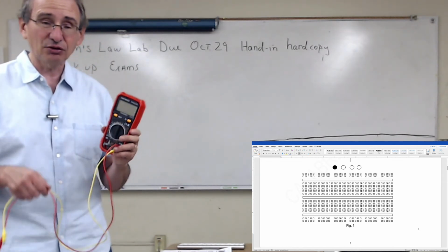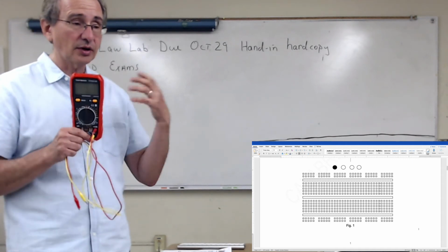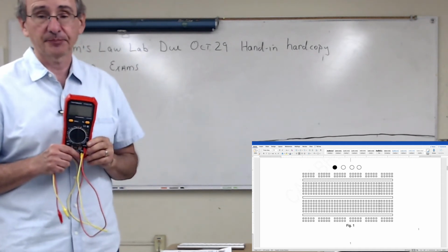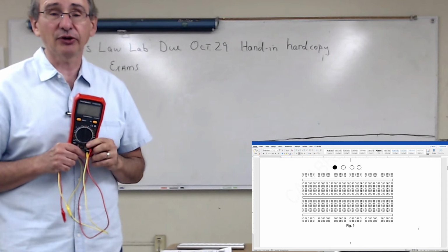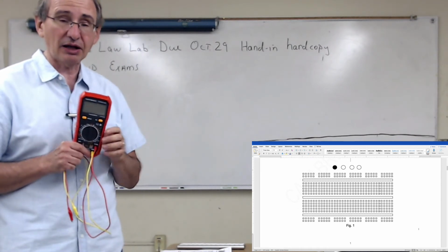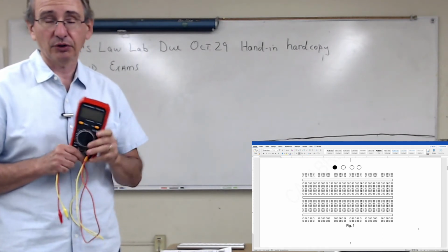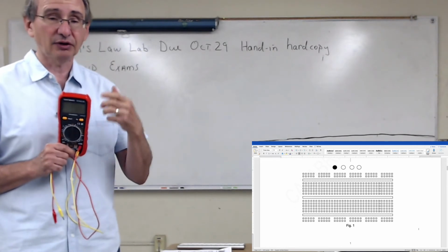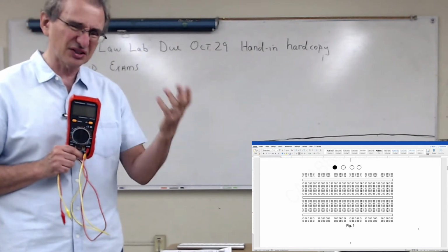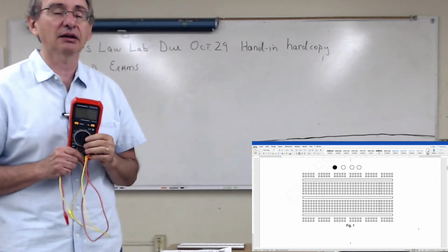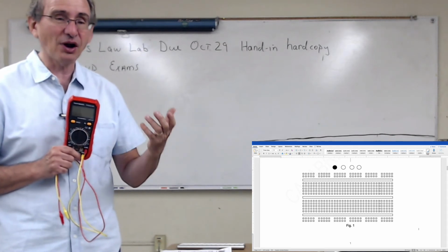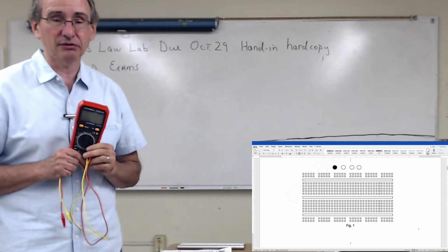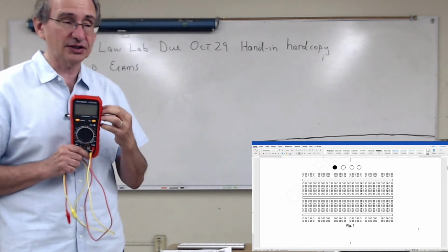But let's say you have 2 multimeters. One of the multimeters stops working. You suspect the fuse. You take the fuse out, and with your second multimeter, you measure the resistance of that fuse. If the fuse resistance is 0 or close to 0, then you know the fuse is okay. If it's too high, then you know something's wrong with the fuse. So you can use this as a diagnostic tool.